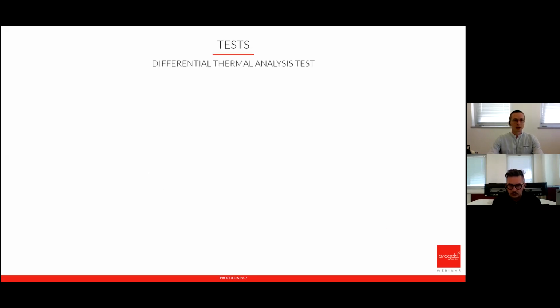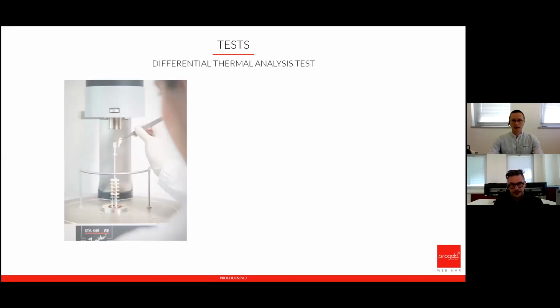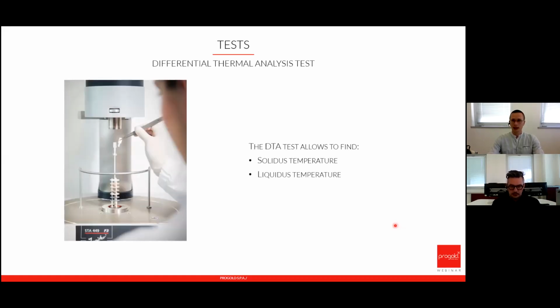The first test we perform is the DTA analysis. We determine the solidus temperature and the liquidus temperature, which are very important in order to cast the alloy, both for casting alloys and wrought alloys.